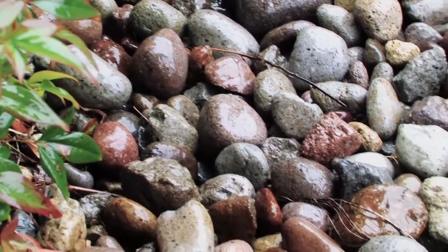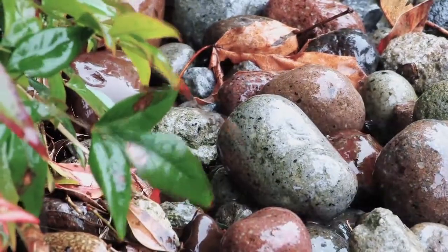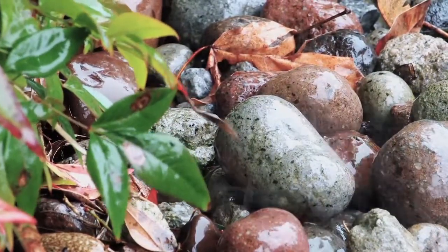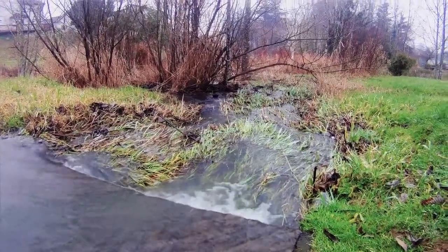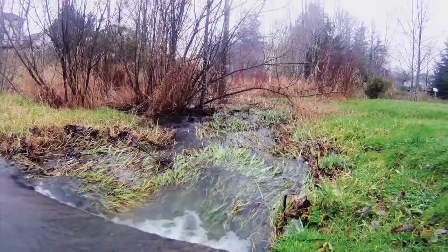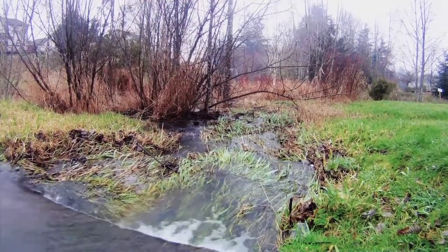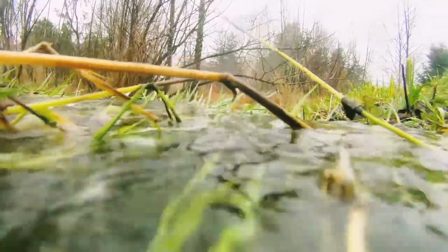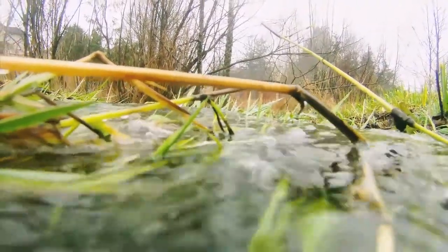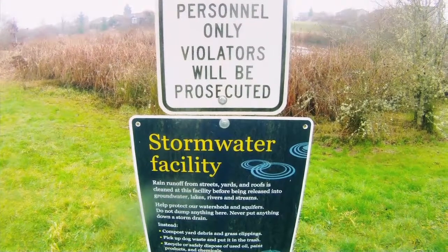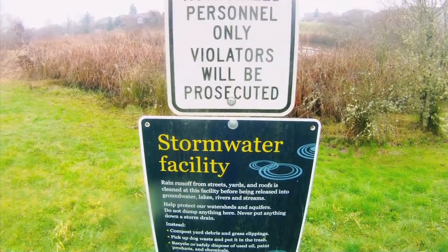The methods and techniques in the rainwater management credit involve minimizing disturbed areas on the project site, limiting the amount of impervious cover on a site, and then infiltrating, filtering, storing, evaporating, or detaining rainwater runoff at or close to its source.